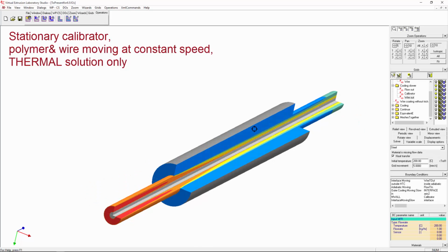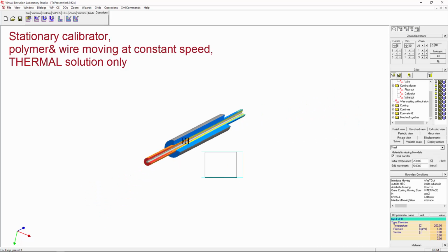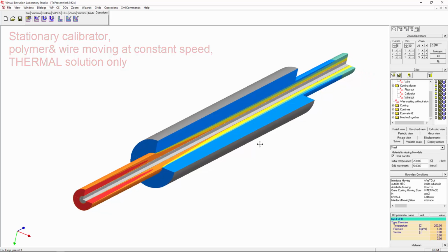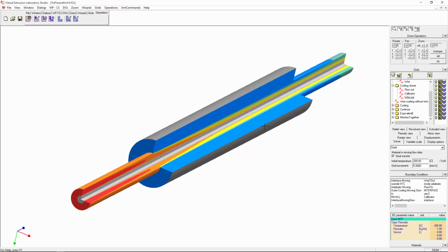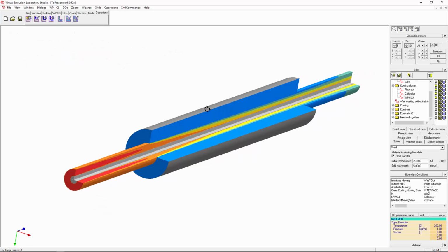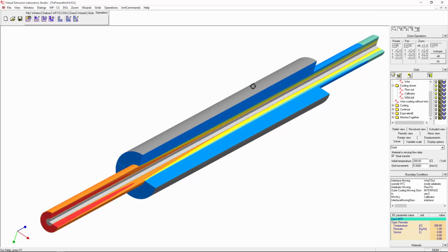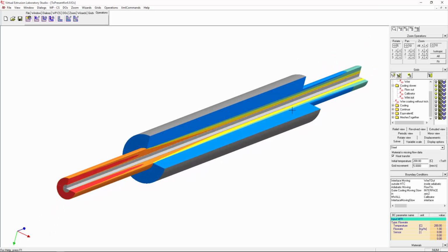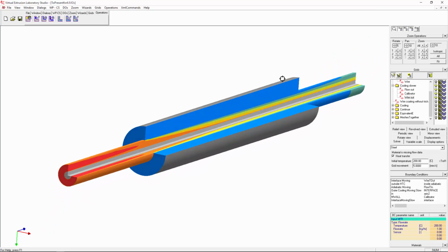And this is quite interesting functionality, that we don't have to have a flow calculation. We can do only temperature calculation. If you want to see diffusion, if you want to see how your die heats up based on different heat sources, or what is the heat transfer inside, you can certainly do it. Another possibility is you can calculate with the temperature your flow situation.